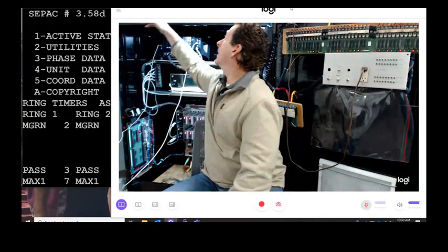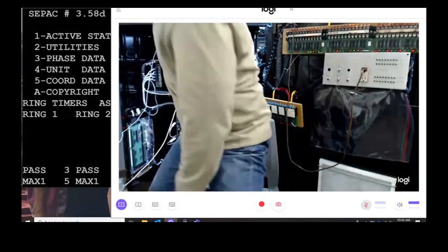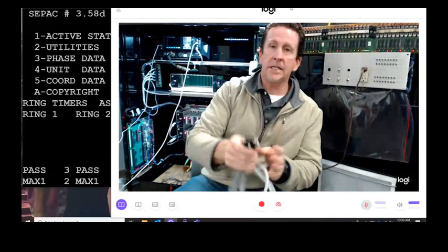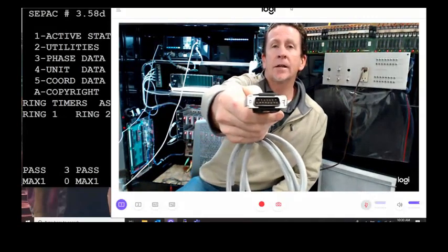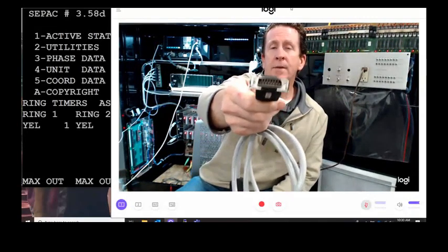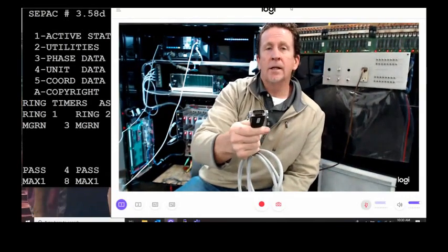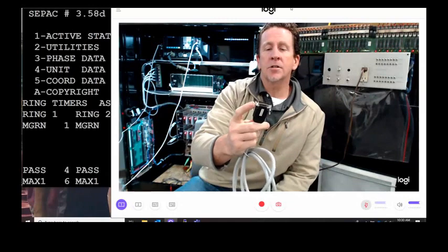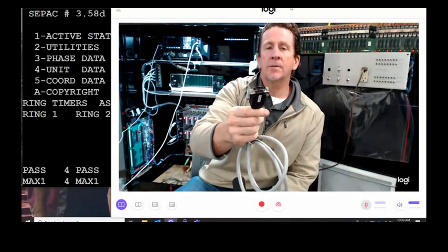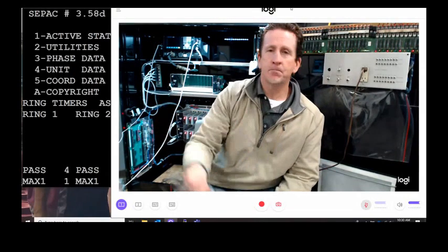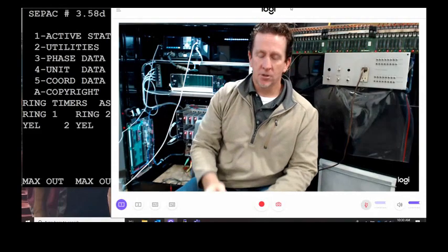One other thing in the cables is these little pins that are in there. The pins break, and they push back in. It only goes on one way, but if that pin isn't seated or there's something loose in the connector, sometimes just having that pin pushed halfway will give us the failure that we have. So it's always good to look at them.